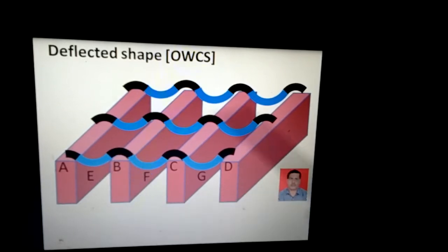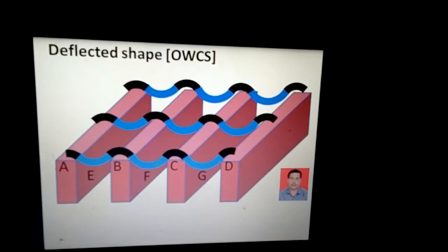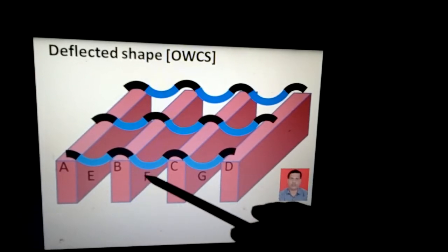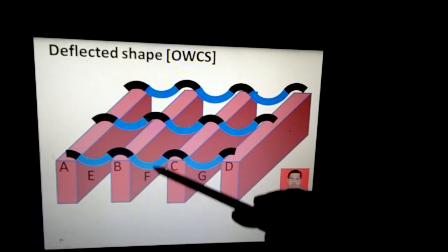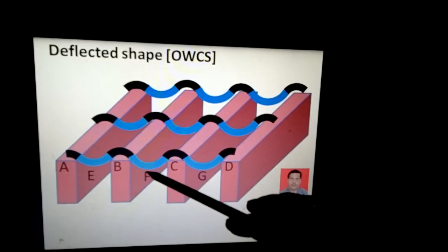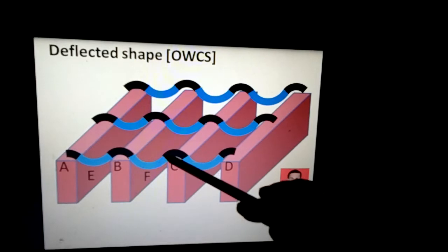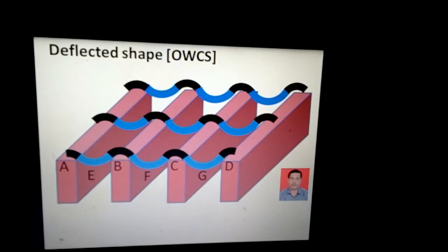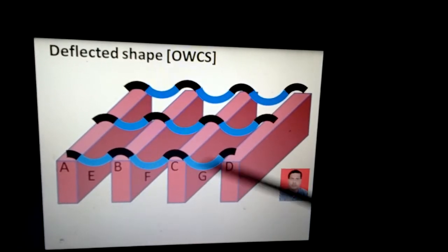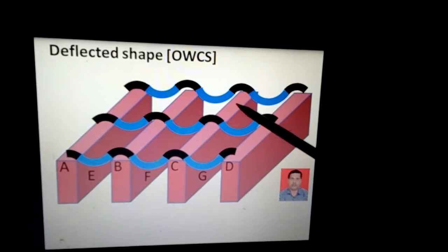So this type of bending of each span is going to exhibit where the reinforcement is needed and at which portion. In the mid span area, it is required at the bottom of the slab, and near the support area it is required on the top of the slab. So the whole span throughout its length Ly is going to have the similar type of bending.